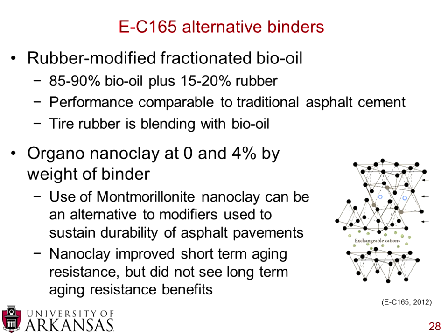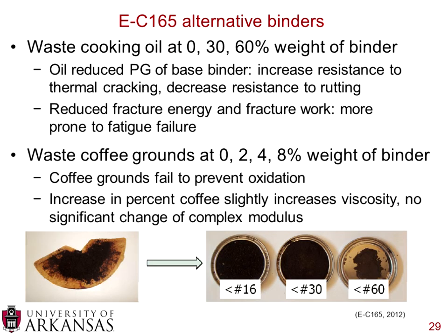characteristics of the material. And they found that they improved the short-term aging resistance, so kind of during the production and construction. In the first couple of years it didn't age as quickly, but then looking at longer term, especially when they started using the PAV, they did not see as many aging resistant benefits. So it may help a little more short-term, but long-term they didn't see as many benefits.